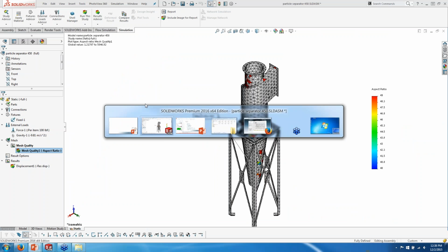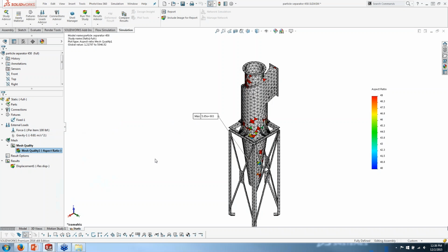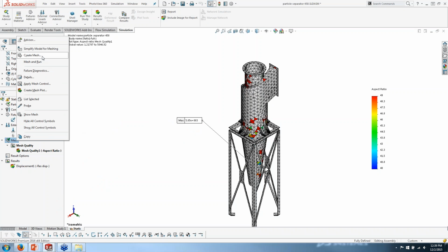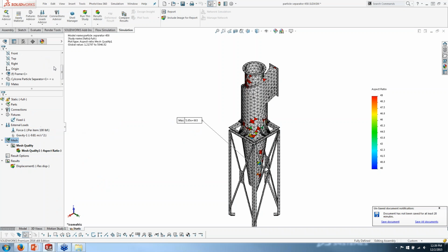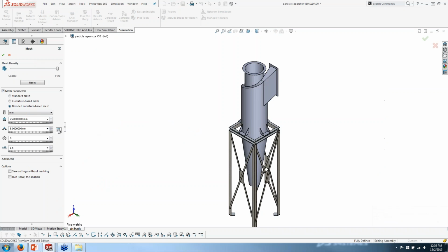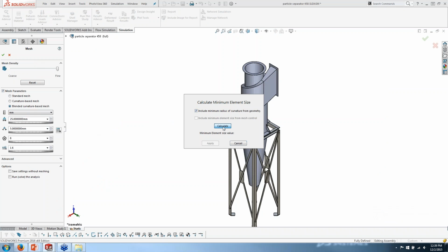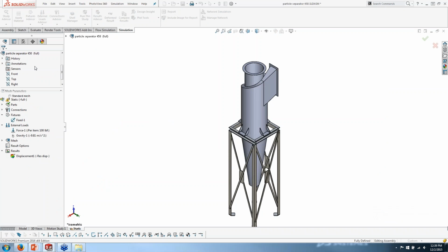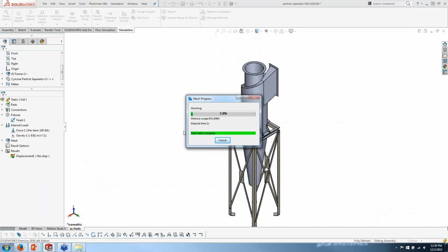Okay, so continuing then with this example, what I like to do then is maybe we can reduce the aspect ratios. This aspect ratio we're seeing is around 5,000. Okay, which can compromise the accuracy of my results to some extent and also make it a little bit more inefficient to run this. So if I go ahead and just cut this mesh size in half perhaps, and I'll use that same calculated size, I might see a lot better aspect ratios this time around.